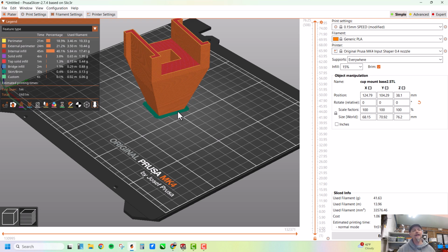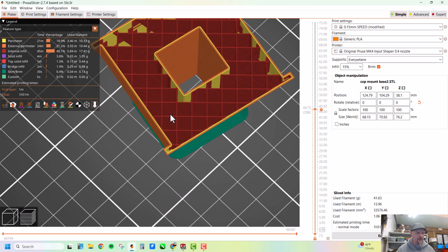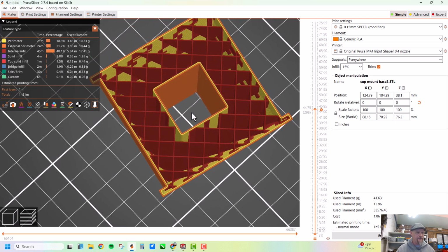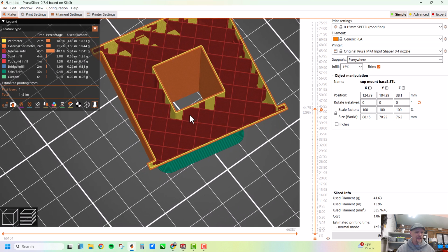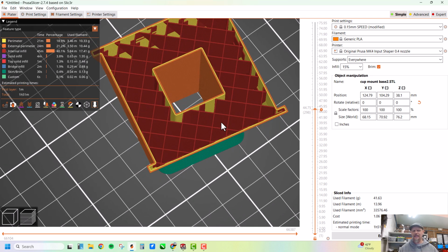However, if you want faster results, or smoother, better detailed, more accurate results, sometimes you want to change these different system presets here. Maybe you want to make your part really lightweight and you're not worried about strength. Well, you could go to a lower infill. I'll show you what that does. Even though this was a solid part in SolidWorks, it filled it with this grid pattern and kept it fairly hollow. That's called infill.